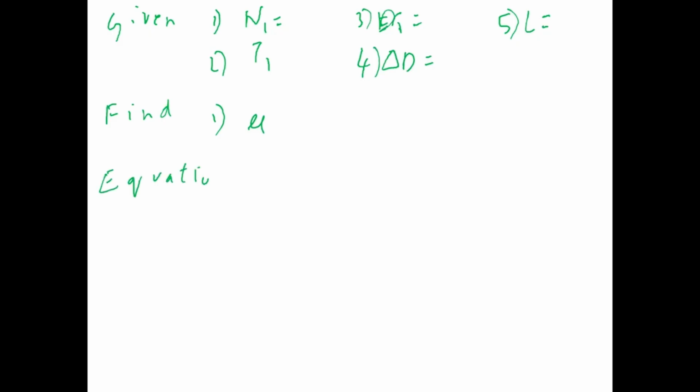If we go back to what equations we can use, we realize we mainly have one relationship that we have learned so far, and that main relationship is that the shear stress is viscosity times du dy, right? If you know the shear stress, you can find force. How do you find force from stress?